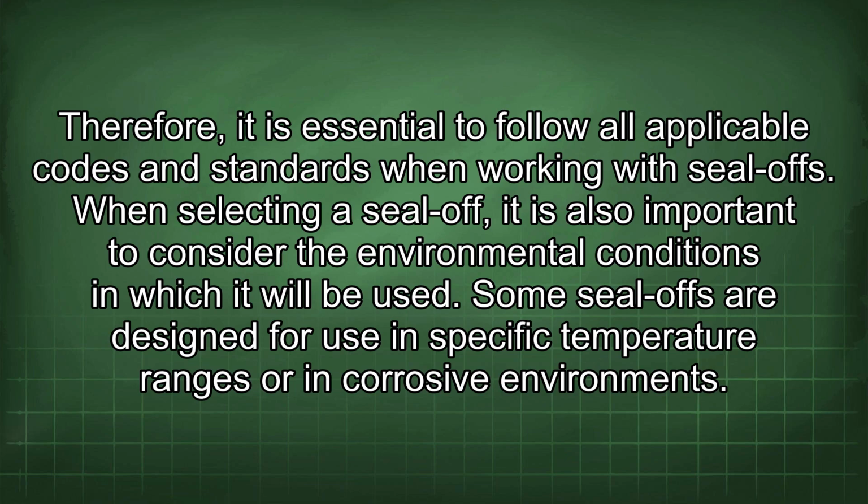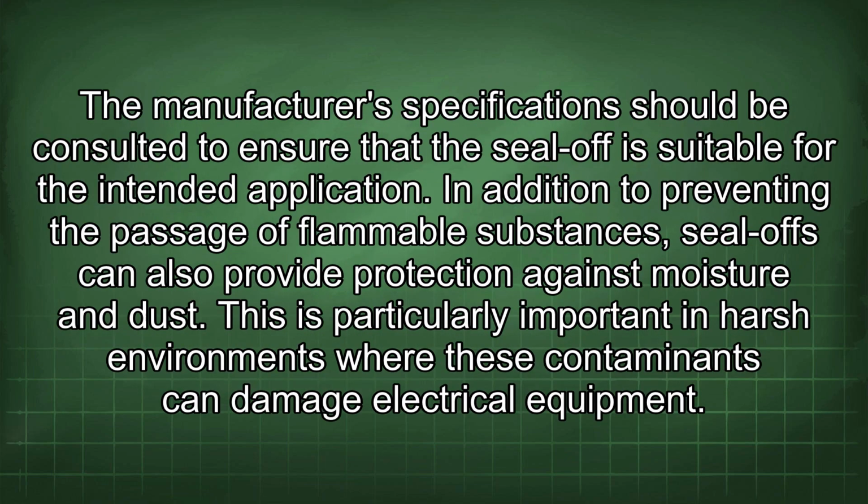When selecting a seal-off, it is also important to consider the environmental conditions in which it will be used. Some seal-offs are designed for use in specific temperature ranges or in corrosive environments. The manufacturer's specification should be consulted to ensure that the seal-off is suitable for the intended application. In addition to preventing the passage of flammable substances, seal-offs can also provide protection against moisture and dust. This is particularly important in harsh environments where these contaminants can damage electrical equipment.